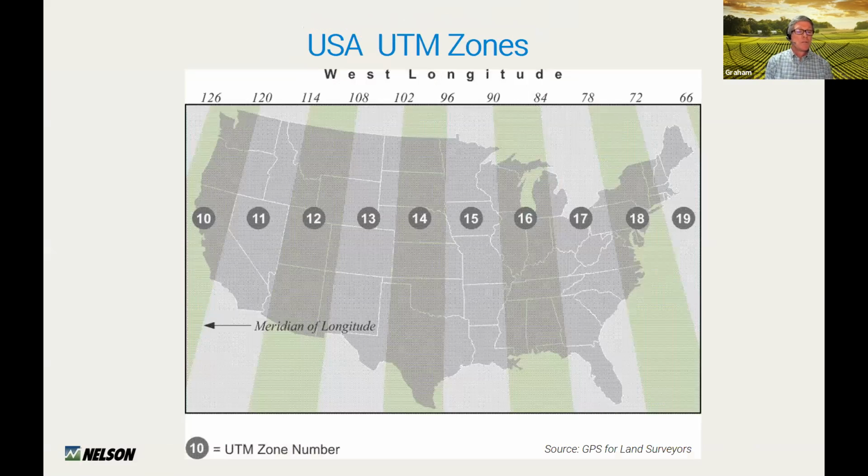Here are the UTM zones within the United States. And when you import data, particularly from Google Earth, the UTM zone will come with it, and you really don't have to think about that. There is a setting within IRRICAD that we will look at, and we'll mention the times that you do need to use it.